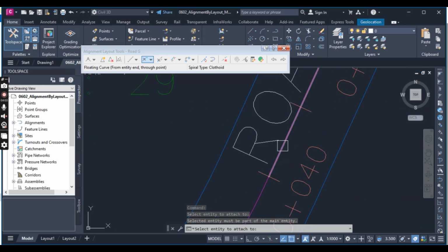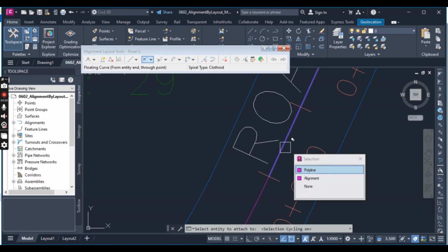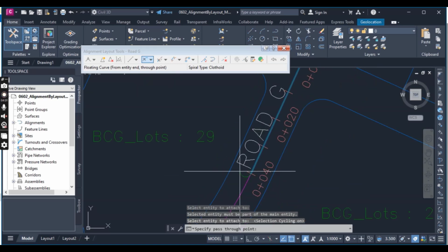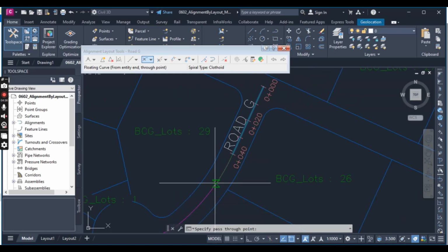You can see it is not selecting this time. Make sure you select the line segment somewhere south of the segment's midpoint to connect to the southern endpoint instead of the northern endpoint. If you cannot select the alignment segment, enable selection cycling with Ctrl+W and try to select again. Here you will see the alignment picked from the end of our previous fixed line entity.